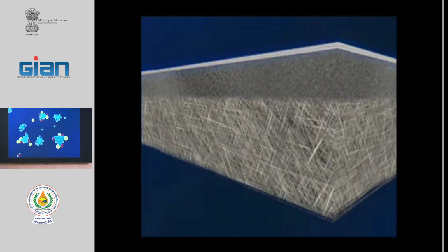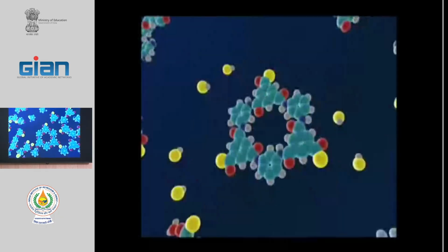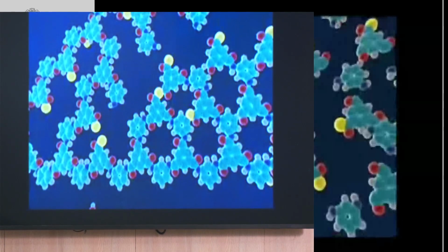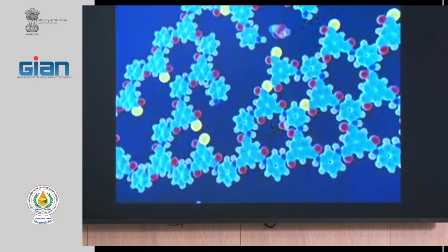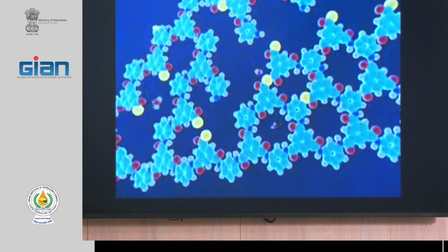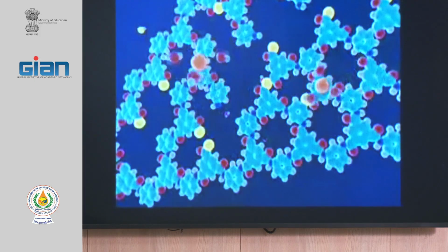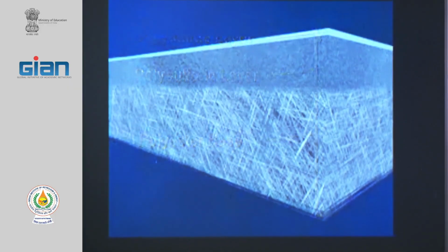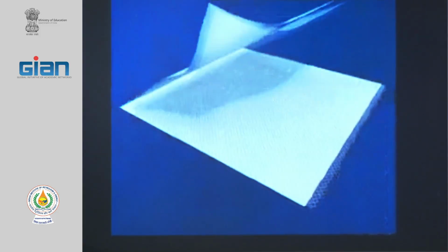For fabrication of RO membranes, we use interfacial polymerization, which I will discuss tomorrow. When these monomers connect together, we have some pores. The water can easily pass through these pores, but the hydrated ions, sodium or chloride, cannot pass. The combination of these 3 layers makes a durable membrane flat sheet that is used in each spiral wound element.